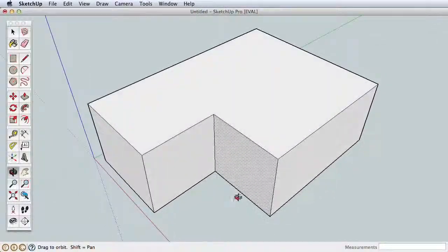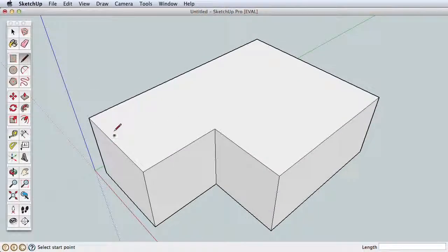To create the roof, we'll use the line tool and draw all the edges we need before pulling the ridge up. Using the line tool, find the midpoint and start drawing back in the green direction. This will be our first ridge, and we need it to connect exactly with the second ridge. To do this, simply hover, but don't click, on the midpoint here, telling SketchUp we are interested in this inference point. Once you see the tool tip telling you it's the midpoint, follow the original green direction and SketchUp will infer to the new midpoint, telling you exactly how far to draw the first edge. Make sure you see both inferences and click to finish the first ridge. Then draw the second ridge to this midpoint.